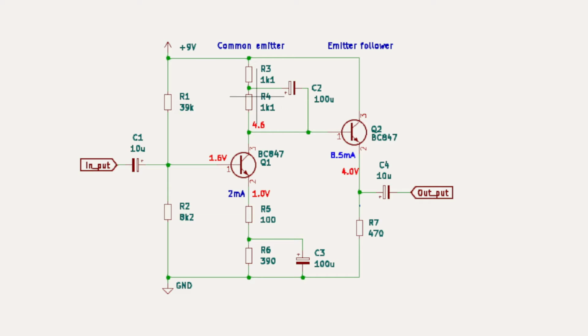So effectively, at low frequencies, or at frequencies where this is virtually 0, it's out of the equation, completely bypassed for AC. So all it's really done is lowered the collector impedance, which effectively, when you take that divided by that, has lowered the gain.